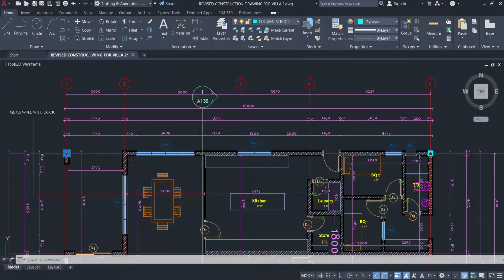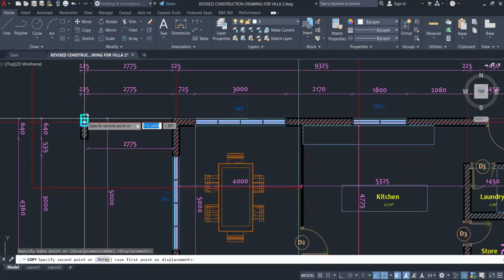So now, if we start from this axis, we've already placed a column here. So let's now move to the right hand side. If we move to the right hand side, you see that there is no wall here on the ground floor. The next wall is far, so this column is isolated on the ground floor. So it will make sense to put another column at this corner. I hope you are following me. To put another column at this corner.